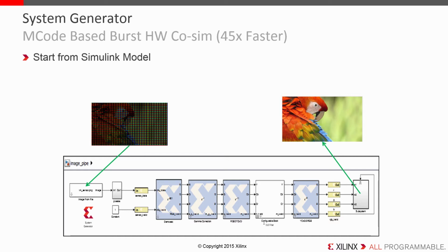There are currently two supported co-simulation target interfaces, Ethernet for the KC705 and VC707 boards, and JTAG. The issue faced by many was that the JTAG implementation was too slow and Ethernet was not supported for their board. In the Vivado 2015.1 version, we enabled burst mode for the Ethernet-based flow. In the Vivado 2015.3 version, we've added burst mode to the JTAG-based flow, which can greatly improve the performance by bursting data to the board, processing in parallel for many cycles, and bursting the data back to the model.